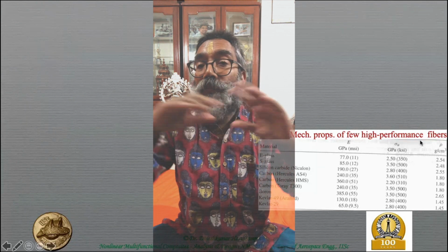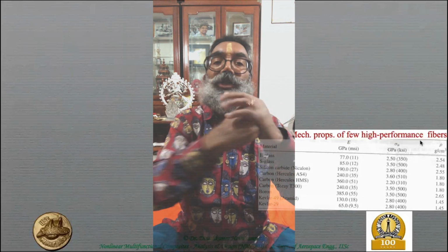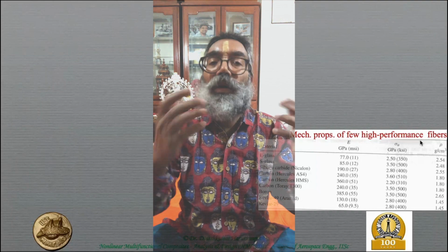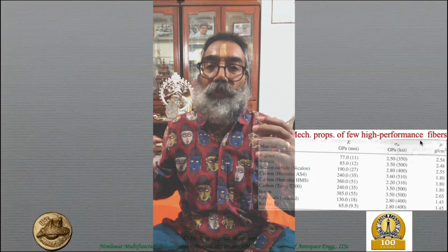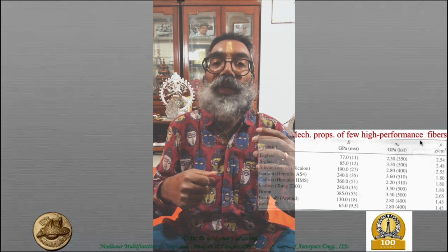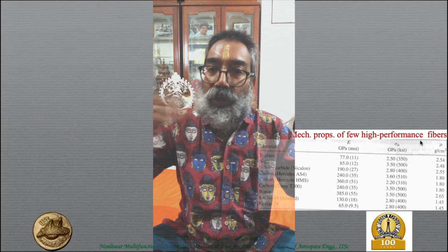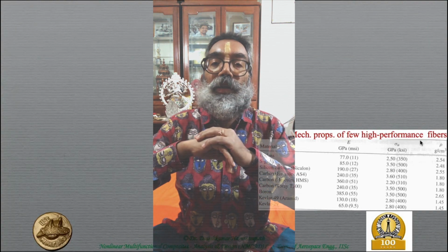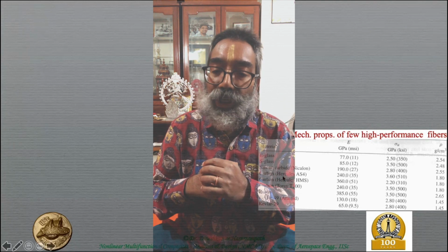So you can use such a fabric as a structure which is primarily designed to take impact loads. Again, it cannot take any bending, it cannot take any compression, but the impact load that is coming is basically creating predominantly tension along the plane or the surface of the fabric, and therefore that is able to take that load to a large extent.